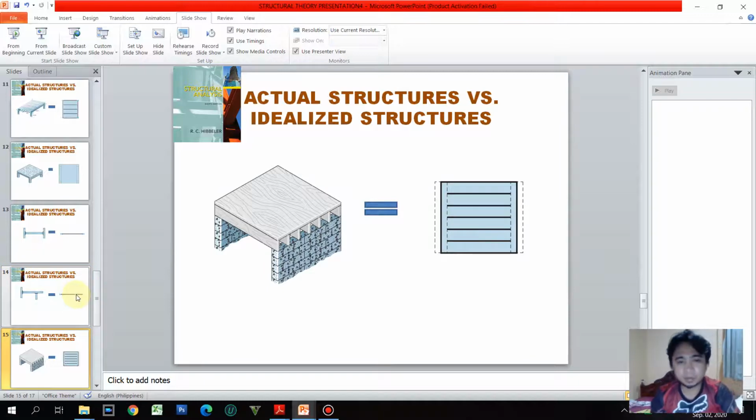So another example, we have here a block, and then on that block we have floor stringers resting on the block, or concrete hollow block, and then on these floor stringers we have the plank. So to indicate that in our top view, we would want to have a dotted line for the column or hollow block support, because it is resting on the bottom.